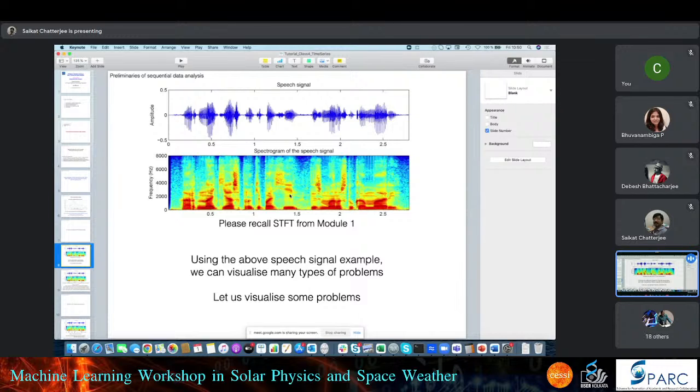But most of the time you do a little bit of experimentation and use your domain knowledge to fix the time window length. Generally we use tapered windows. One of the standard windows is Hanning, and there are Bartlett windows and others. Lots of research is done, and the windows are chosen such that the leakage of the power spectrum is low in its side lobes. Maybe this is too technical, but it is some kind of tapered window, and these windows exist, so you can simply call them and use them in your program.